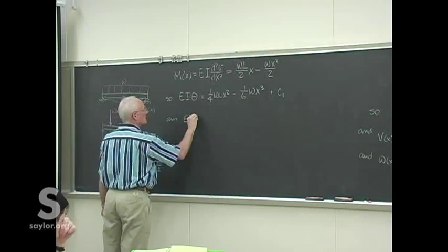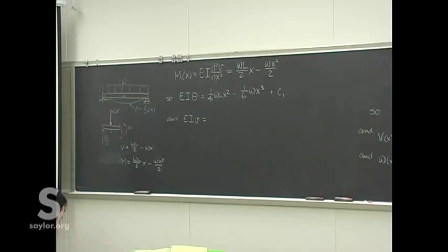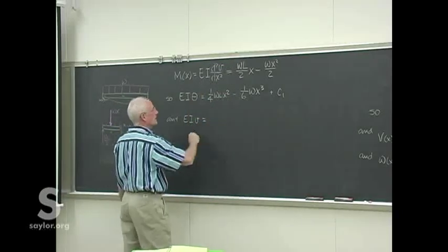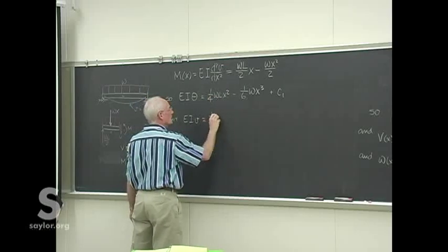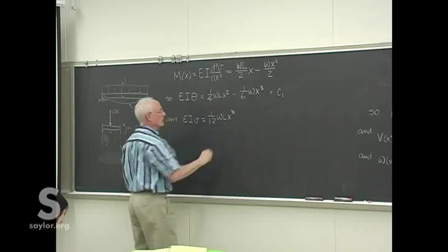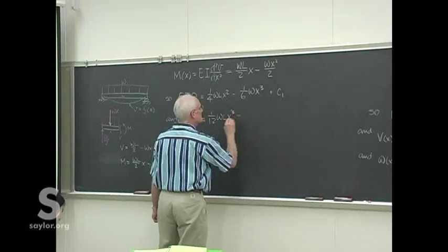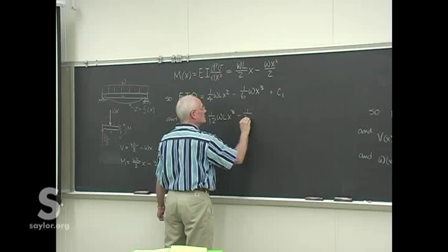And then we can get to the deflection curve with one more integration of that equation. All we're doing is marching up the line of equations there. So this becomes a 3 when it comes down. We get 1/12 WLx cubed. Right so far? Okay, can't lose any minus signs, can't lose any powers. So this becomes a 4. We get 1 over 24.